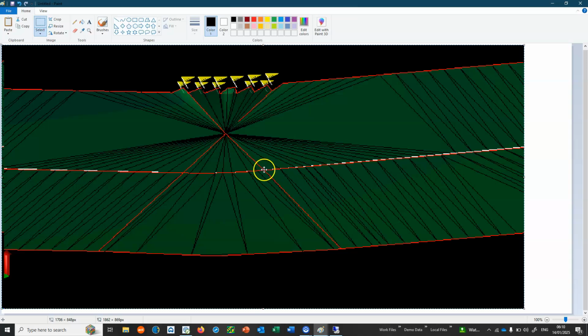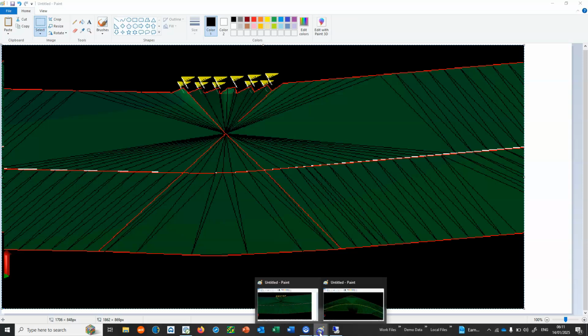So if, for example, this is 10 meters and we go positive chainage to chainage 10.5, we can see that it actually regresses on the channel line. Sorry, 10 meters chainage on the channel is here, and 10.5 on the channel is here. So we're getting a regression, which should never happen in a road design, and then we get this erratic functionality.